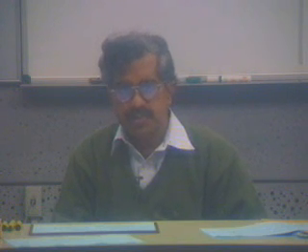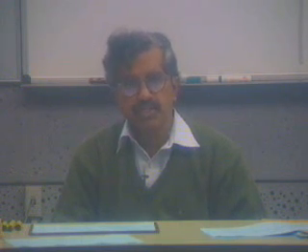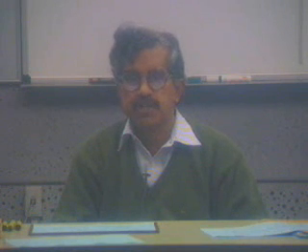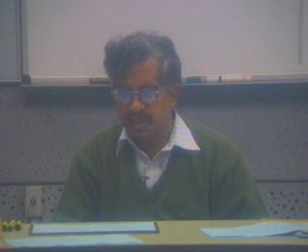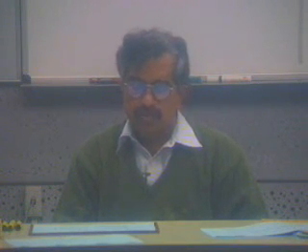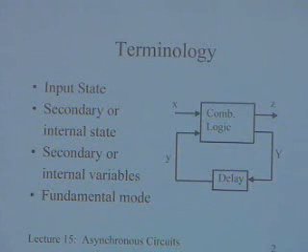And the fundamental thing about synchronous sequential circuits was there was a clock, and each time this clock appeared, you transferred the next state into the present state. So the clock was the timing which was responsible for transferring, so that when we talked of s(t+1) and s(t), this relationship of t+1 and t was established through the clock. That is, the next state will become the present state once the clock comes. When we talk of asynchronous circuits, there is no clock. That is a fundamental thing. So we do not have a clock as an input over here.